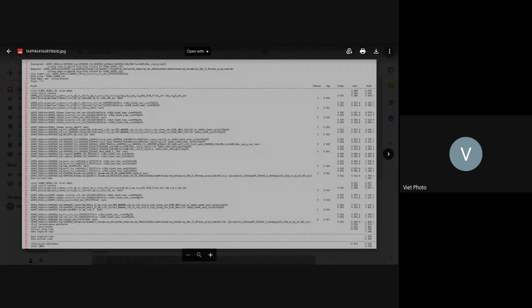Path group, path type max. Max means the setup check, min checks the hold time. Now you see it starts from the clock, at 0 here. Then when it goes to the first line, there's the transition, which is the transition time of the signal. After that I cut it here, because the three dots mean there's a lot in between, but I just want to show this part.